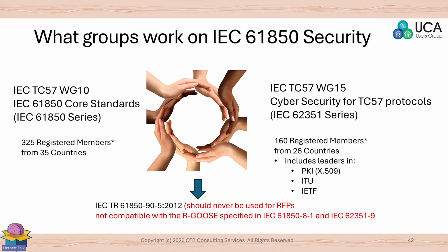And guess what? Most of the core standards defer to Working Group 15 and then bring references back to the core standards by referencing the appropriate 62351 series standards. So if you ask, is there a 61850 standard for cybersecurity? No. The answer is specifically that there are 62351 standards for 61850 security, and 61850 references those.